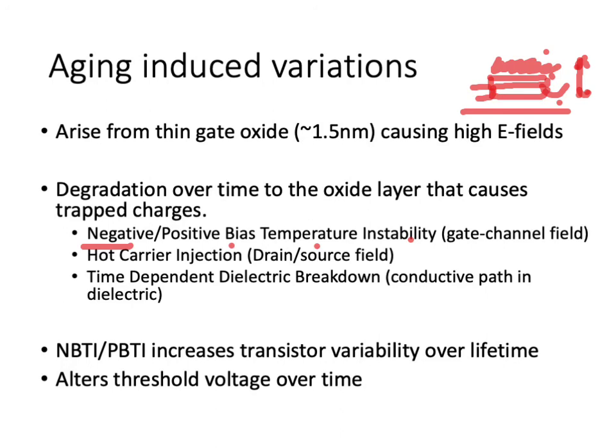So the goal of this slide is just for you to have a general understanding that there are these three major breakdown mechanisms due to three different sources of electric fields or physical mechanisms, but really it's the problem of charge getting trapped in the dielectric, a very thin dielectric layer in the transistors, due to high electric fields.